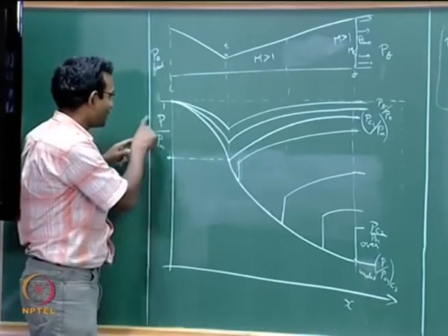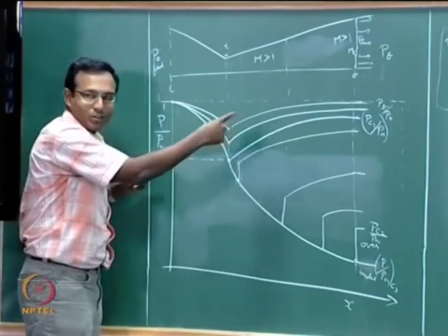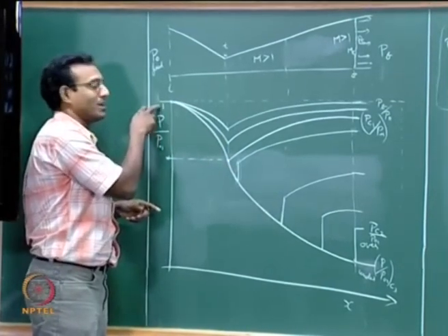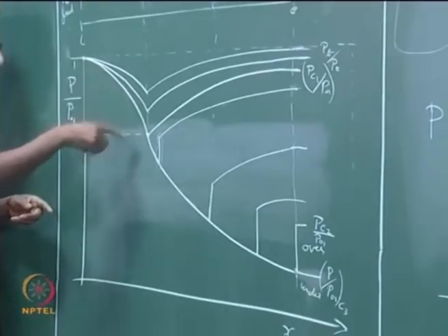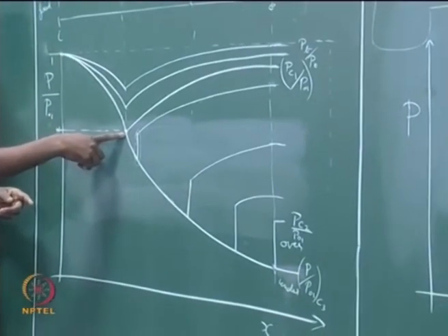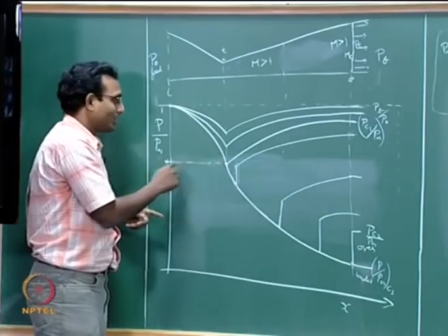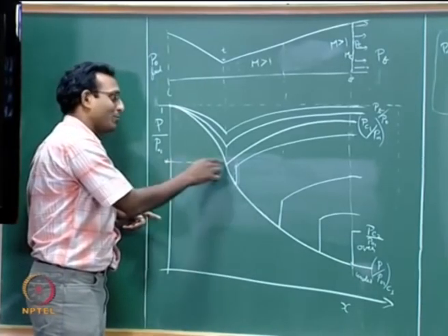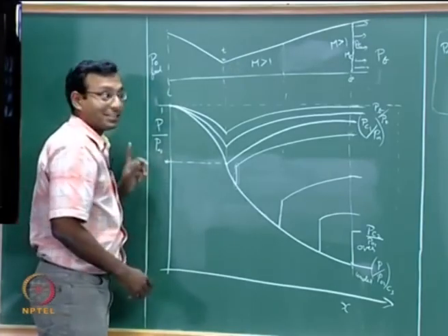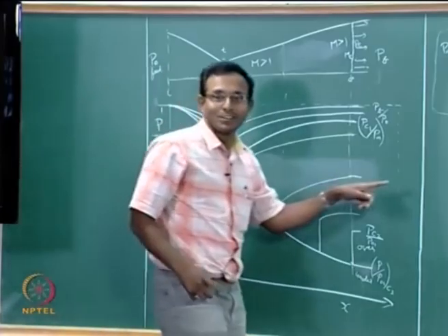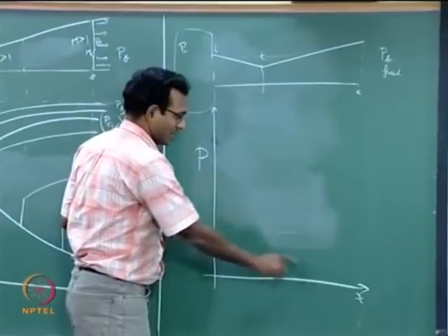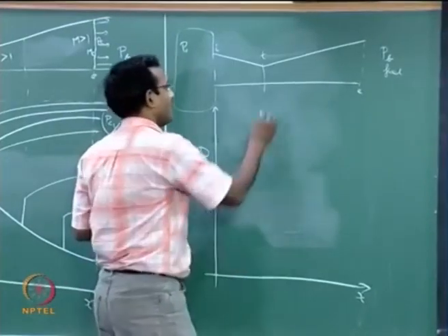Okay. If I multiply this whole thing, every point on the plot by a P naught 1, that is just equivalent to multiplying this 1 by a number P naught 1, and similarly if it is say 0.8 P naught 1, 0.5 P naught 1 for gamma, right, gamma equal to 1.4, it is 0.53 something. So, it is going to be 0.53 of P naught 1, that is all, nothing changes, it just scales this plot. That is not the case when I change the denominator. So, I will go and plot it again, I will just plot pressure versus x in this case. Okay.